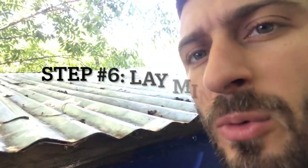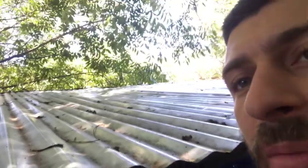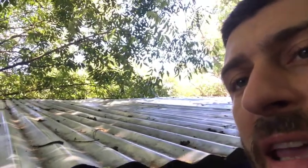The process for laying mineral wool bats on the roof is the same as the process for laying them on the sides of the house. You can lay them flat on the roof here and then use the batten strips to hold it down to the roof, and then ultimately you just lay your corrugated metal or roofing material on top of that.